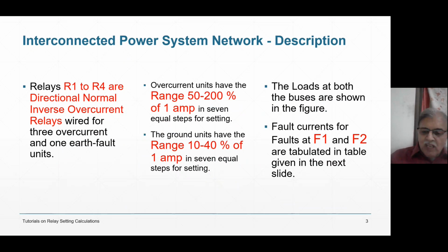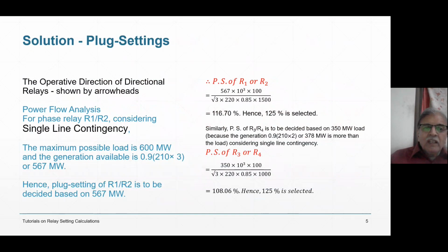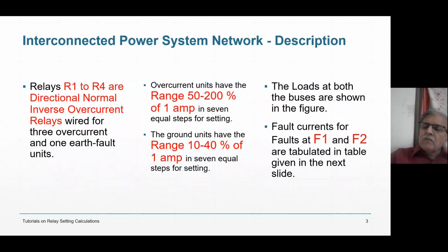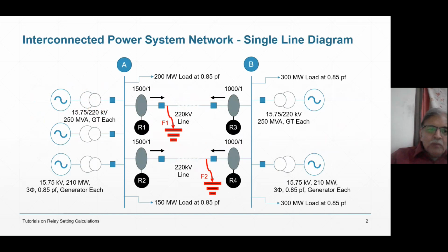power is being used. I think it was given somewhere that 10% of power is being consumed by the auxiliaries. It is not given, but you have to assume obviously that 10% of power will always be consumed by the auxiliaries, right? Auxiliaries will consume some power, because for running 210 megawatt, you have to run a boiler. Boiler means boiler feed pump, condensate extraction pump, CW pumps, right? The FD fan, PF fan, ID fan, and whatnot. Many things you have to run.